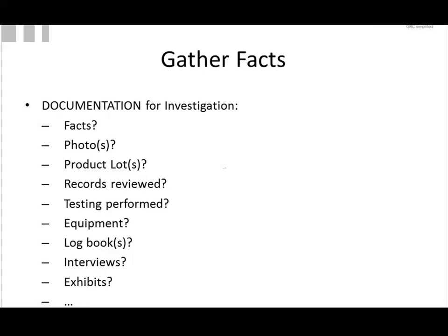Photos are good across the board. If you're looking at failures on parts and maybe reoccurring failures in the same location, some photos to put in the file would be useful, and then that'll give you a point as to where in the manufacturing or molding process or whatever that type of defect might be introduced, allow you to go back to it.